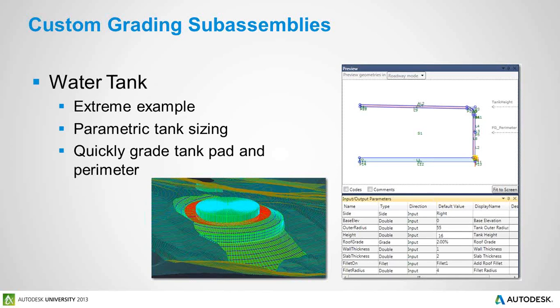It's a water tank design model that we did. It allowed us to put in all of the tank elements with their own parameters, so we could change the base elevation. Instead of editing profiles, we can edit the elevation value relative to the alignment profile around the perimeter of the tank. We can sink it down into the ground or raise it and lower it. We could adjust the footing depth, the height of the tank, and the slope of the roof, which I played with a little bit for pictorial purposes. But then we also had different parameters where we could do a finished grade, where we'd actually do a profile around the perimeter of the tank, so we could put in grades for drainage and whatnot.